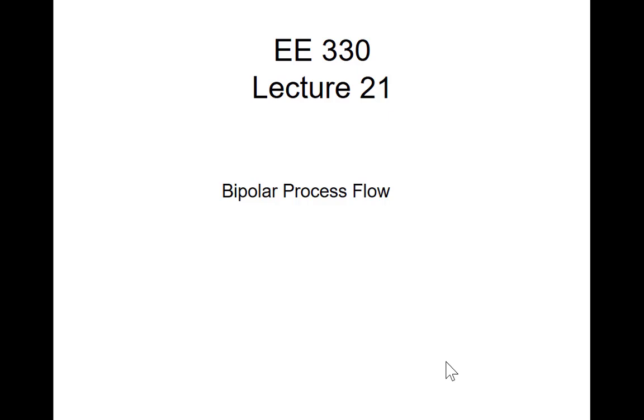Causes current gain from input. So the MOS transistor is a square law device. Its transconductance characteristics are primary. A bipolar transistor is an exponential law device, but it's basically a current gain device. The MOS transistor was conceived first, but the bipolar transistor went into production first, and the MOS transistor now dominates many process flows. However, there are a lot of ICs still built today with the bipolar transistor, primarily because that exponential relationship between the controlling variable and the output is very attractive for many circuits.